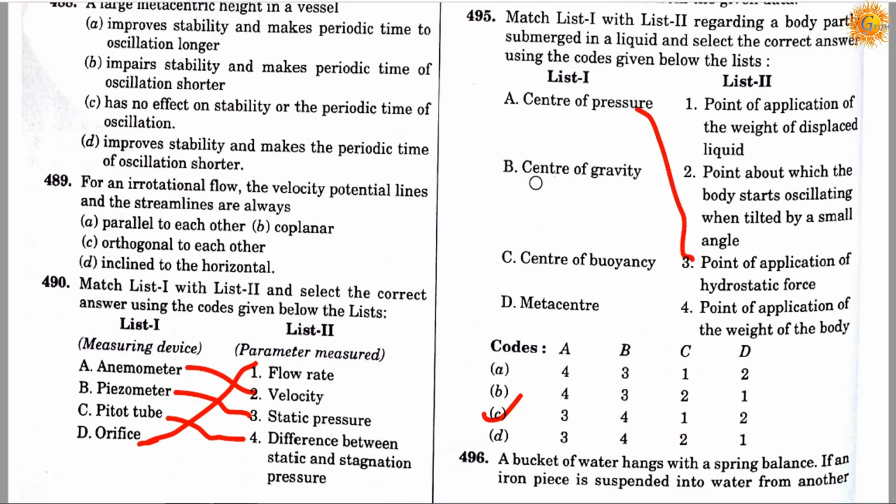Center of gravity will be connected to the point of application of the weight of the body, and center of buoyancy is connected to the point of application of the weight of displaced liquid, and metacenter is connected to the point about which the body starts oscillating when tilted by a small angle.